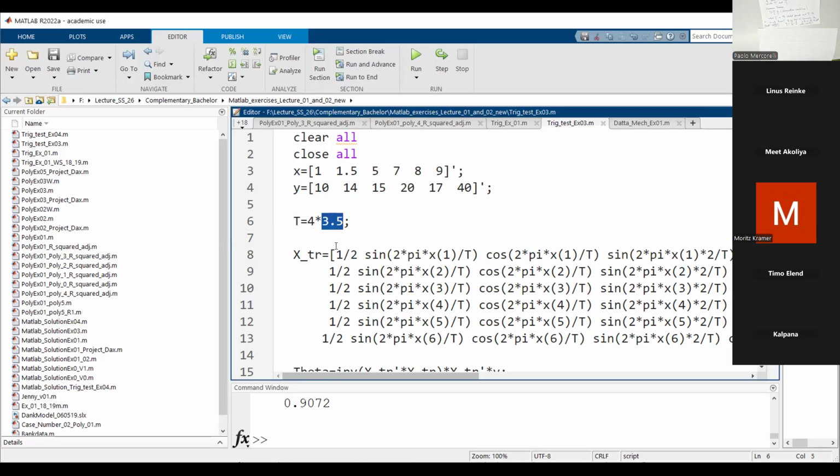Why 4? Because we have two harmonics. I have to consider therefore the fastest one. In this sense, it's conservative. This means larger than this could be possible, strictly larger. With this value here some problems could appear. Why could it not necessarily appear? First of all, it is a sufficient condition. Secondarily, the fastest is not guaranteed, but the slowest, nevertheless, is there. This means the approximation could nevertheless be acceptable. Let me see, but I think some small problems will appear. Let me see.